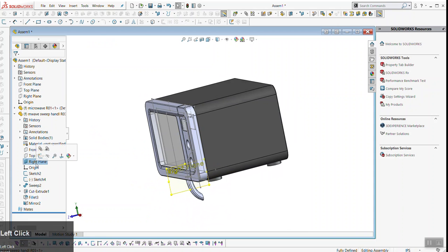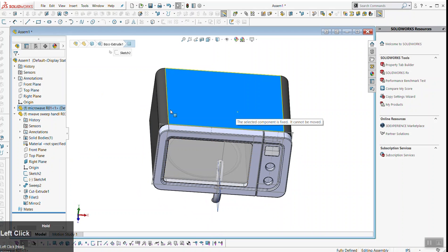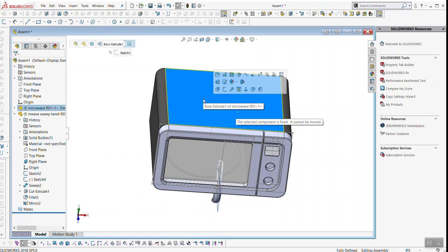So that's the difference. When you click the check mark, it zeroes it on the origin of the assembly. It aligns everything. Now the question I have, I think this is going to, nope, it's fixed. That's the other thing that happens too. When you click the check mark, it comes in as fixed, meaning to say it is paired to the origin and it's not going to move.